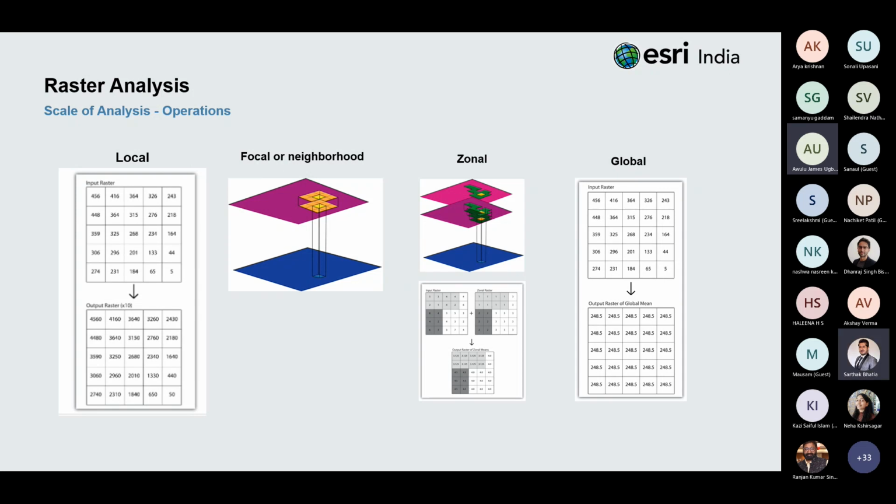Now, in this case, as each cell is processed individually, and as the window moves or shifts along with it to calculate each raster, the configuration generally tends to remain the same. That means the size of the neighborhood remains the same. So does its shape. And specifically, the value of each cell is dependent upon its direct neighbors only. Now, the most typically used neighborhood calculation is a 3 by 3, which means a total set of 9 cells are utilized to calculate the value, as represented in the image itself, which is a pure 3 by 3 in this case.